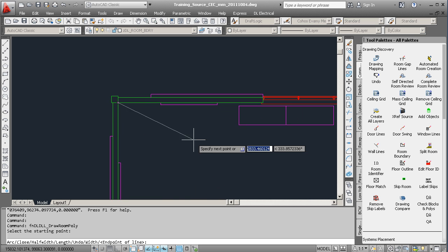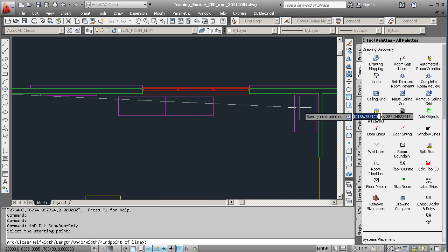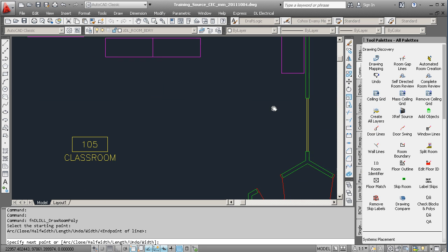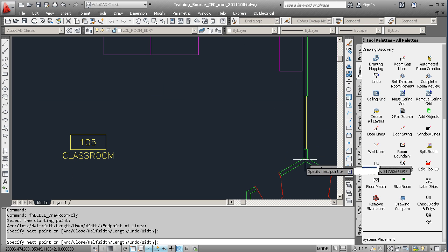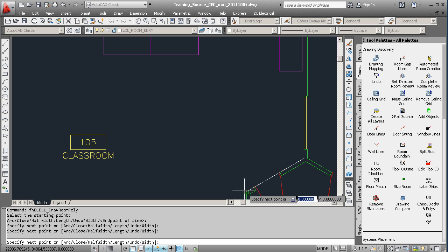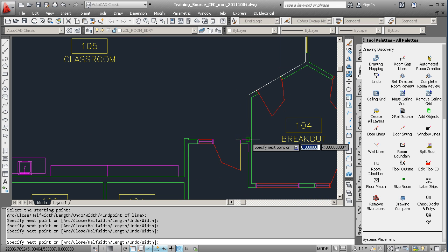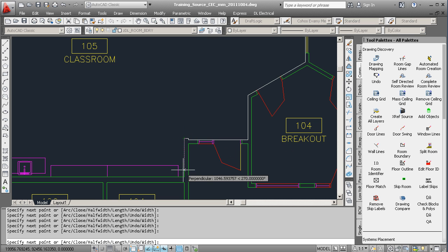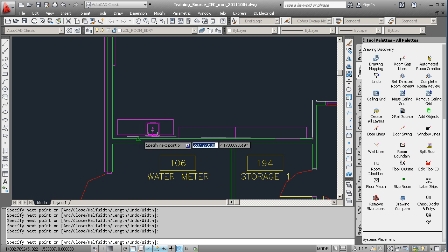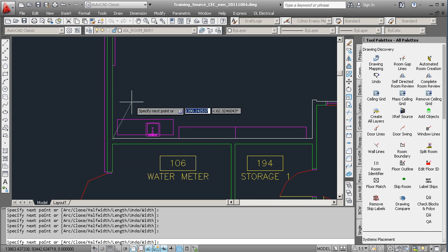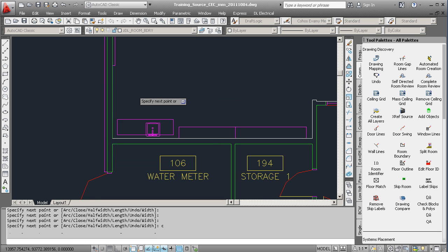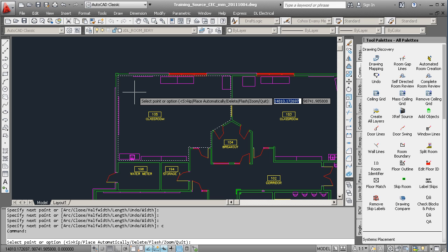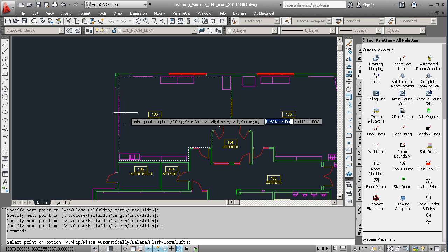So I just quickly use this room boundary tool to draw my inner perimeters, and they don't have to be super exact, but the tighter the better to the inner perimeter of the room. So I'm just going around with O-snap and close that last line with the C command. Very important to do that. Don't click around until you're right on top of your starting point. Always use the C command to close that last line.